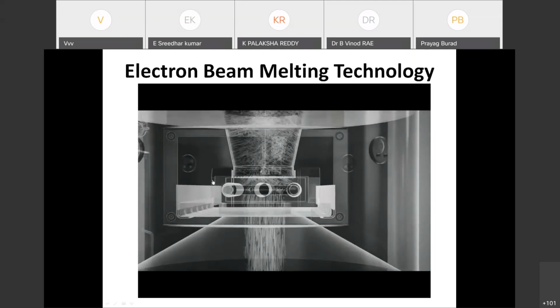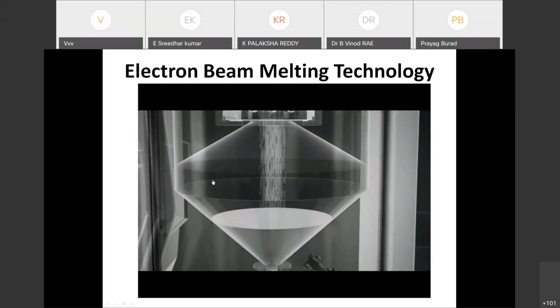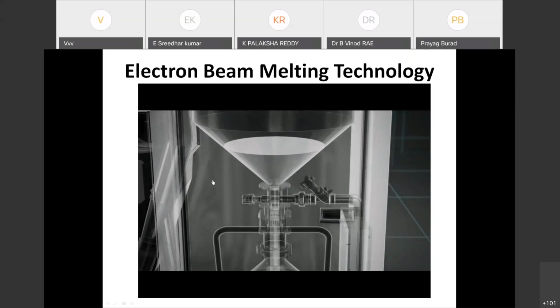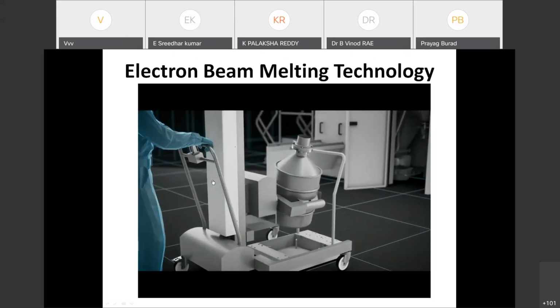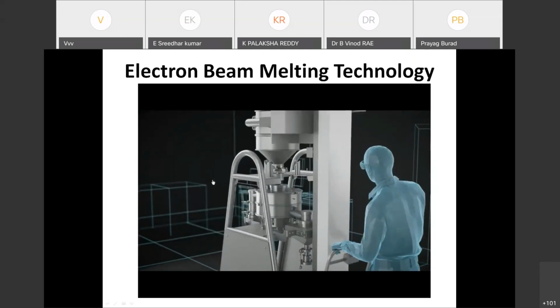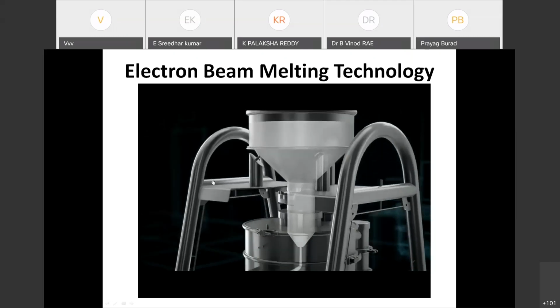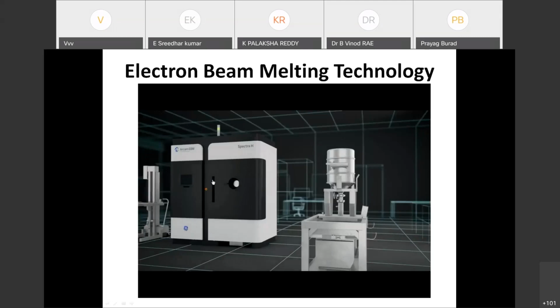If you inhale this powder, it will settle in the lungs and cause a lot of health complications. So it is better to recover it in a proper way. A vacuum collects the uncured powder, and it is kept for rebottling again.